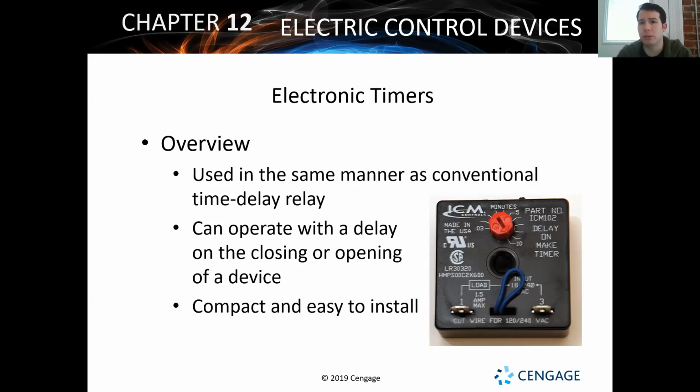These are really good for making sure that a system delays itself. This is also a really good way to stop short cycling. Not just making sure that, yes, the pressure's equalized on an air conditioning or heat pump cycle, but also making sure that we don't have a system short cycling. There we go. Took a minute.